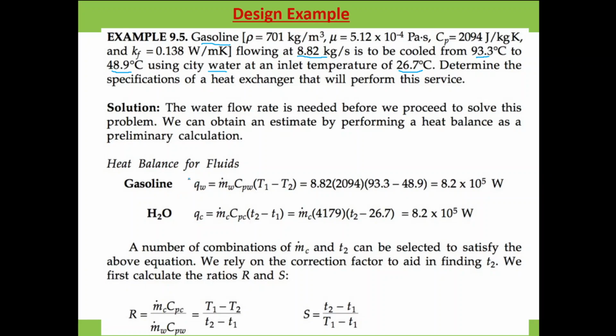We can calculate the rate of heat transfer for the gasoline, since the mass flow rate is given, the specific heat we can get from the properties, and the initial and desired temperatures are given. So the heat transfer comes out to be 8.2 times 10 raised to the power 5 watt. This should be equal to the heat transfer by the cold fluid.